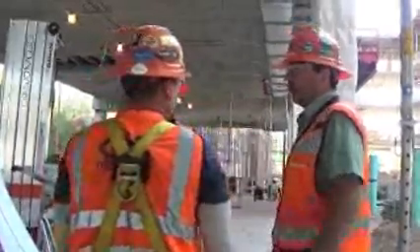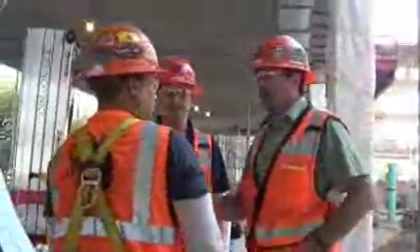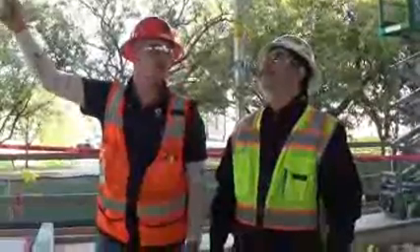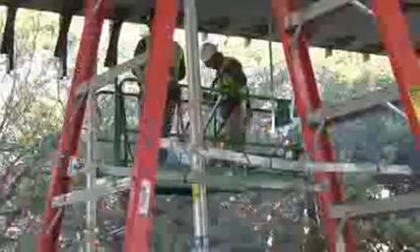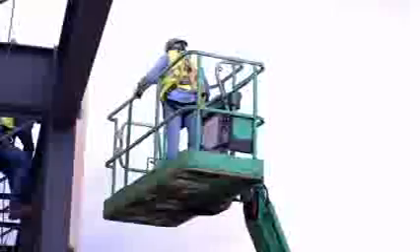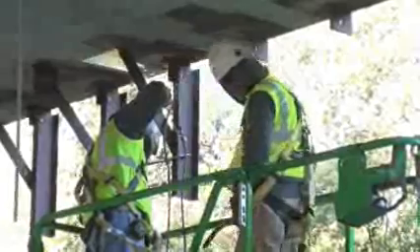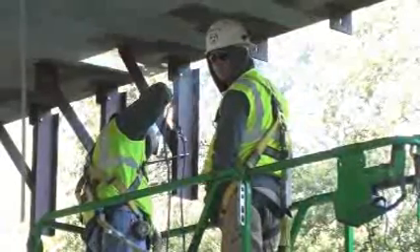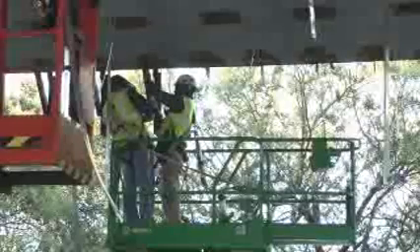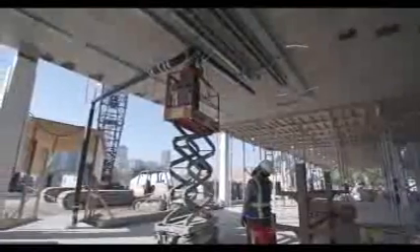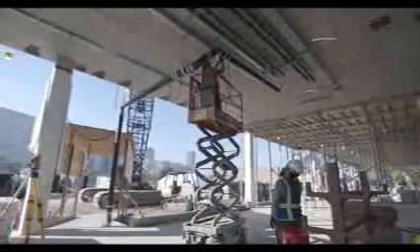A risk assessment must be performed to identify the risks associated with the specific MEWP operations. The risks could be due to the task being performed, the type of MEWP used, or the location of the work. Risk assessment must include identifying the work to be done and selecting the appropriate MEWP to do the work. One must identify the risks involved with the work to be performed and note the control measures to eliminate or mitigate the risks involved. Before beginning work, safe work procedures must be established.